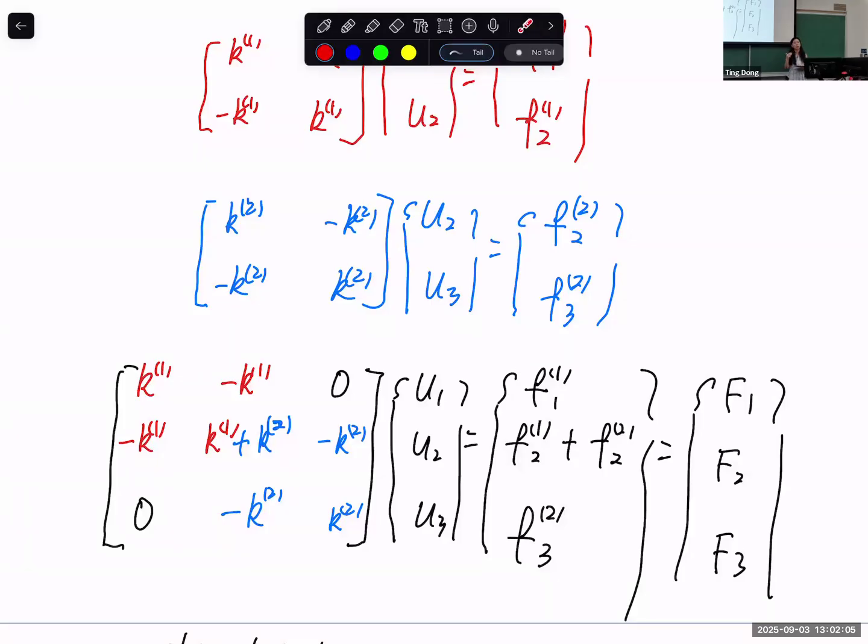Right now we can say that the dimension of the K matrix depends on how many nodes we have. But later, when we learn more advanced elements, it's not really just dependent on the number of nodes. It also depends on how many degrees of freedom at each node. If we talk about a frame element, it has displacement in x direction, displacement in y direction, and rotation about the z direction. So now each node has 3 degrees of freedom. So if you have one frame element, it actually becomes 6 by 6 because the 2 nodes each have 3, right? So yeah, any other question?